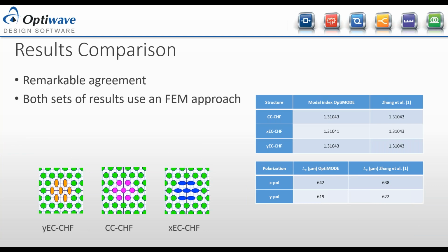For the 3 independent cores, you can see them on the bottom here. Again, they have different core structures but the same cladding crystal structure, the green circles. They have different cores to have the special properties of only supporting an X-polarized mode or only supporting a Y-polarized mode. And then the center core supports both those modes.